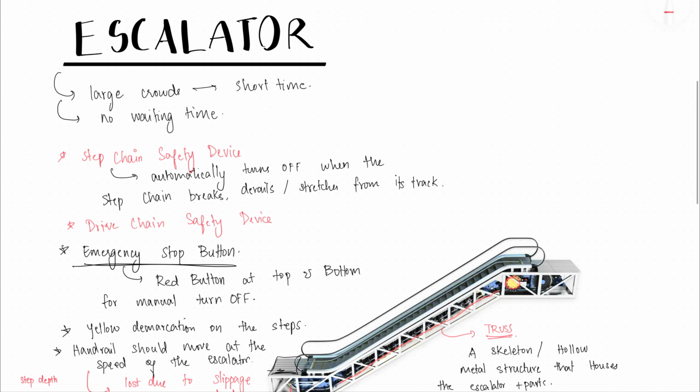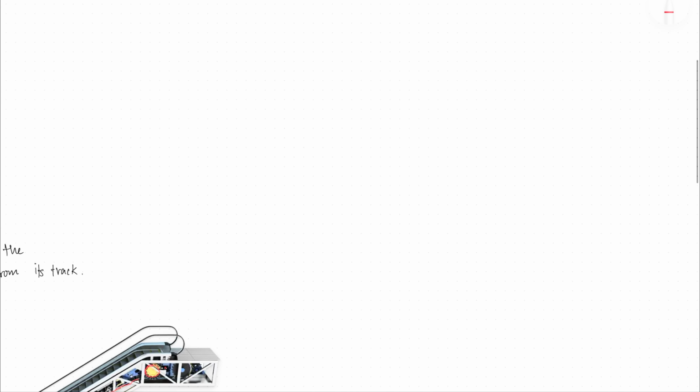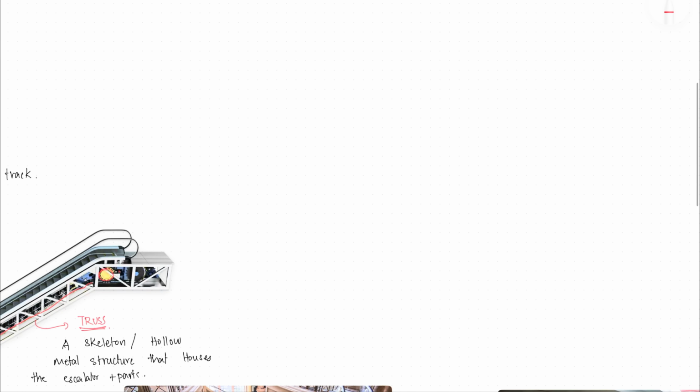And before I step into different layouts, there is one more thing that I want to talk about: your landing on the escalator, right? So imagine this is your escalator. The landing can be provided in two options. You should have sufficient space for circulation of the people who are getting down, and that connects with your corridor or an open atrium or whatever space. But there should be a clear distinction between the landing of your escalator and other circulation space.